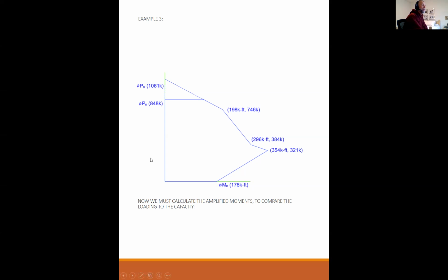The only thing that plays into this diagram are the material properties: the size of the column, the strength of the concrete, the size of the steel, strength of the steel, and dimensioning. That's it. So this is dependent on the section properties of the column only. And now we're about to get to what you do when you go from a short column to a slender column.